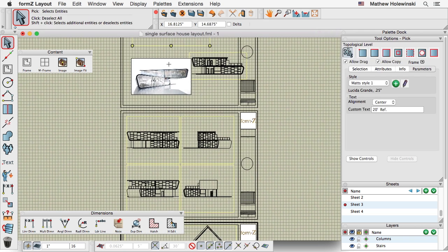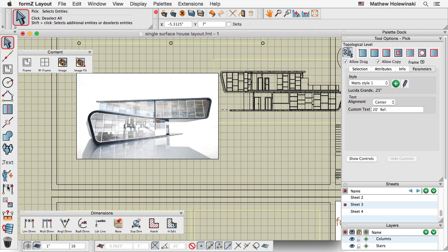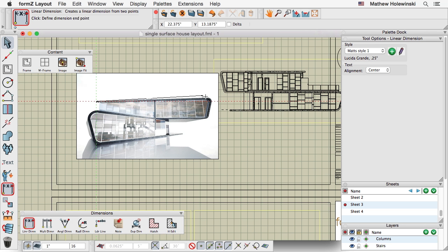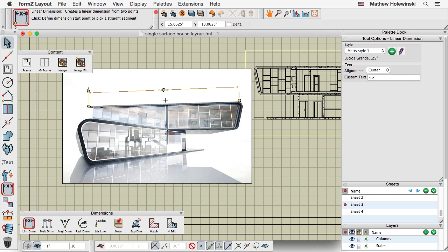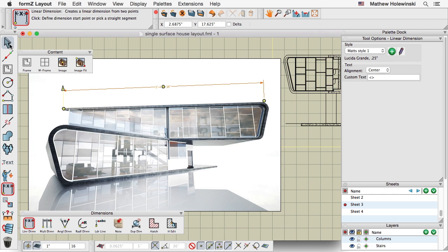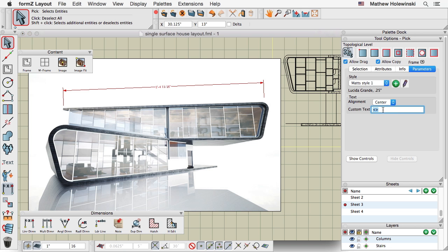So for example, on the image over here, if I want to place a dimension up here, I could say, well, let's put a dimension in the paper space mode because that's not attached to any 3D model. There's no link to a 3D model here. So it's saying that's about 18 inches there, or 16 inches, right? So I can go in there and just modify some information here and get rid of the real paper space information, type in my own number information, and there we go. We can update that there.